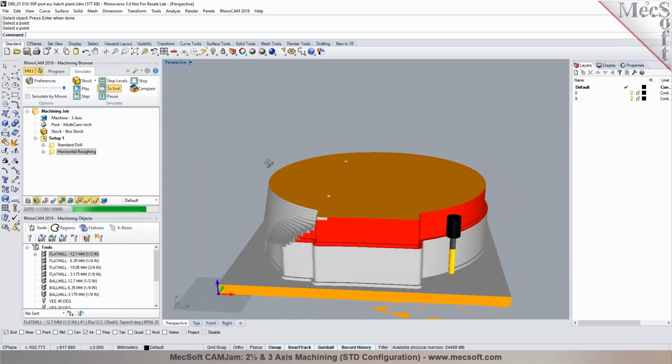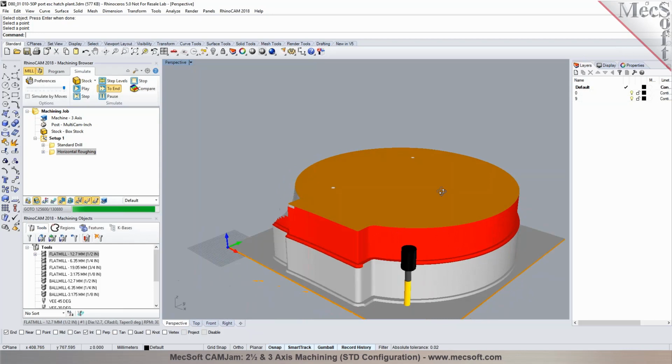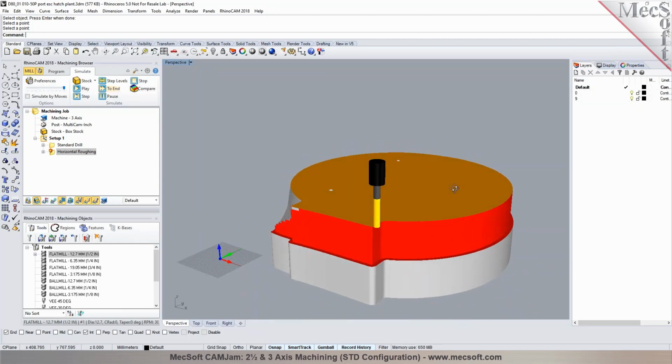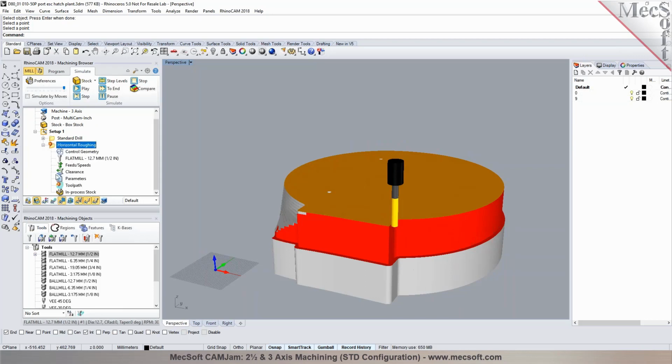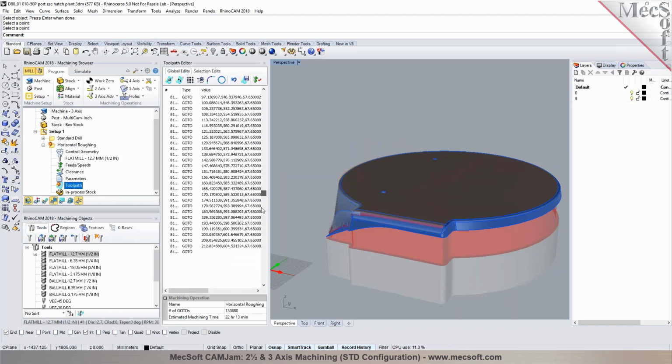That is correct. Yeah. Okay. And it'll also flag the operation as dirty once it's done with the simulation, and it'll mark those toolpath motions in the toolpath viewer. You can actually double click on it and launch the toolpath viewer, and it'll show the lines where there's collisions. If you scroll through here, once you get past a certain area, you'll see all of those collision areas in there. Yeah. Okay. So we should get these guys to use that.